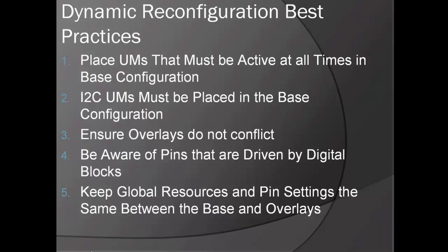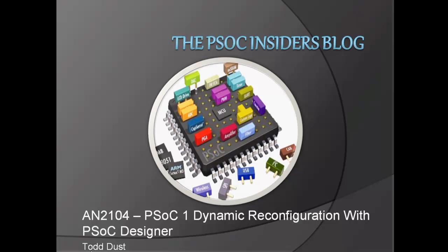Number 5, keep global and pin settings the same between overlays. This will reduce the amount of code needed and reconfiguration execution time. It will also reduce undesired device behavior. For more information on dynamic reconfiguration, including a discussion of interrupts, time to load an overlay, dynamic reconfiguration files, and much more, consult application note AN2104.